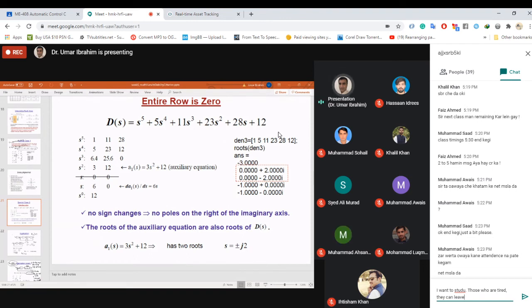Okay. Next, we try to calculate this value from this column and this column, but this also comes out to be 0. Now, if both of these values come out to be 0, and if you use epsilon, still this will not work. This will not be the proper way. If you have the whole row to be 0, you have to replace it with a derivative of this row. So this whole row becomes 0, 0. This is case 2.